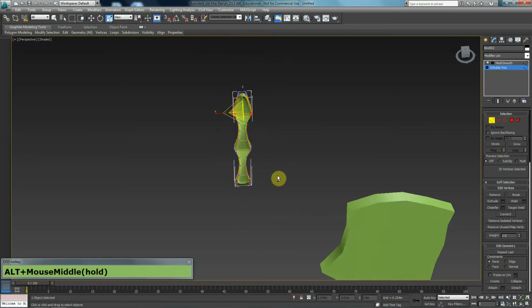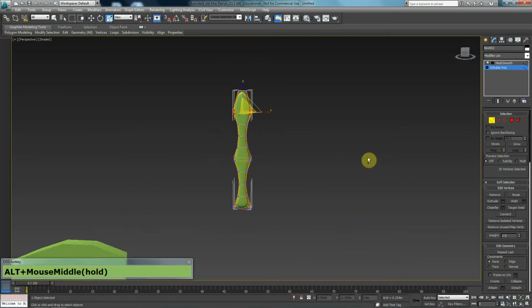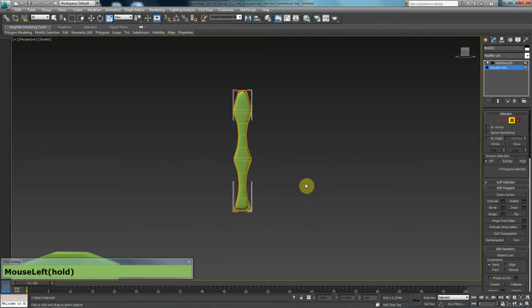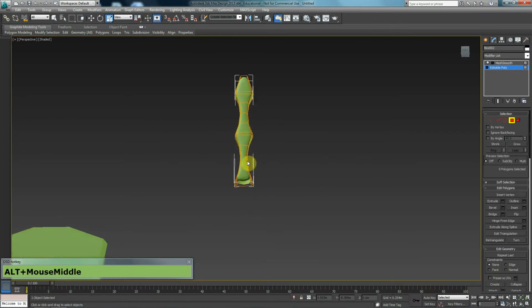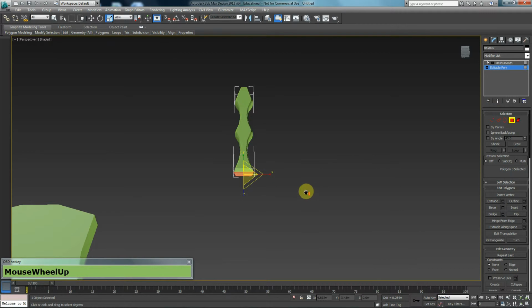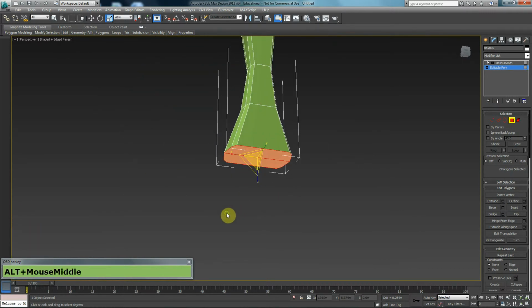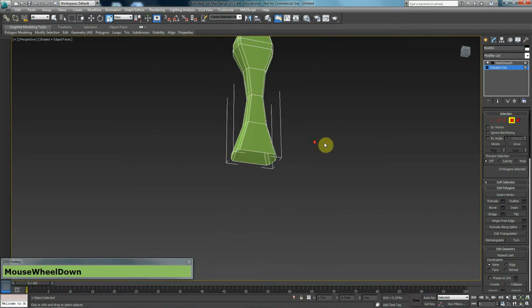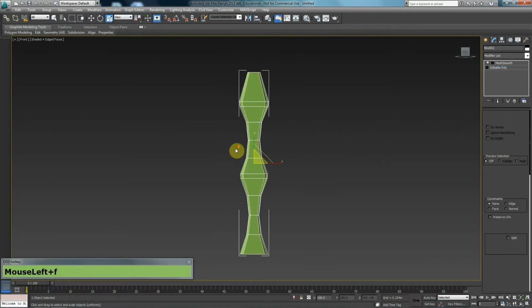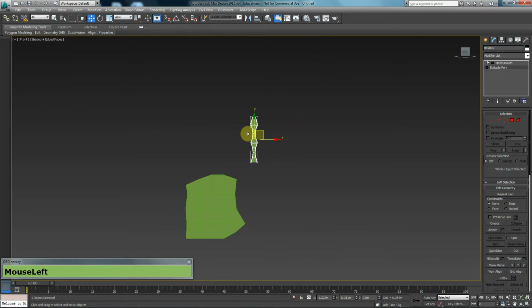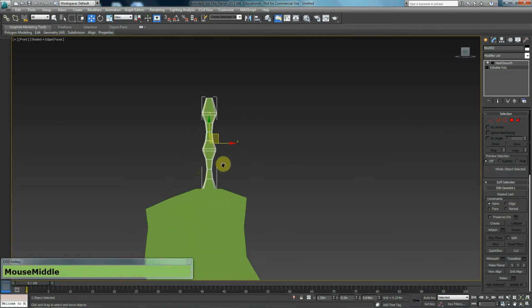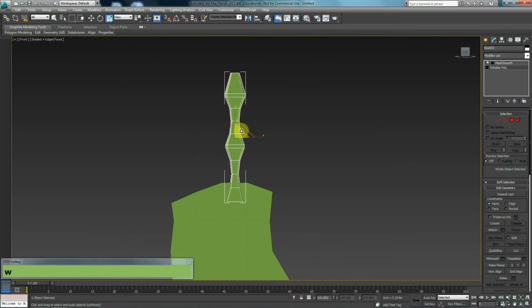Let's just see how it looks in total. It's not too bad, I guess. Also, the polygons at the very bottom, that's where these polygons are going to be welded with the base mesh. So I'm going to delete that, and bring that and put that over here. Of course, it's too small compared to the hand, so I'm going to scale this up.